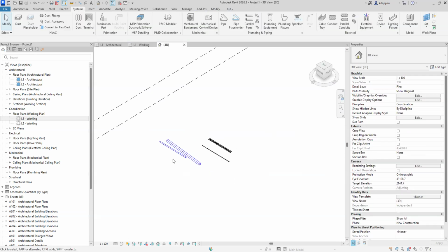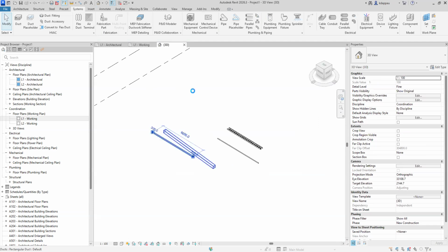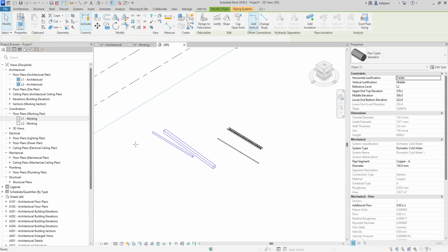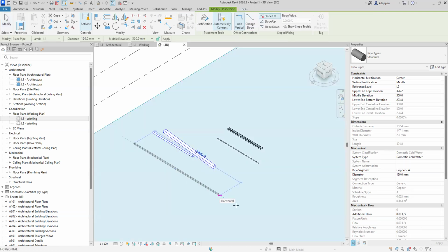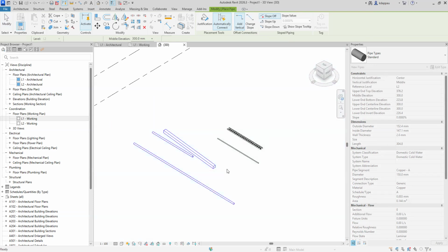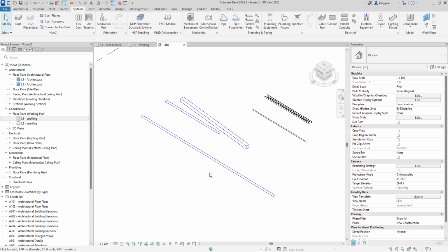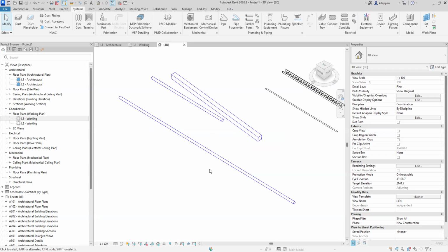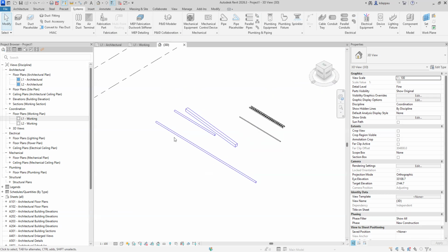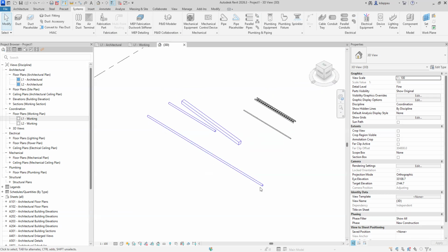So, if you are in Revit and you are drawing pipe, you cannot draw a pipe length of about, say, 15 meters and assume everything is all right. No, you can't do that. So if you want to get a 15-meter long pipe, what do you do? You join. You need joints.